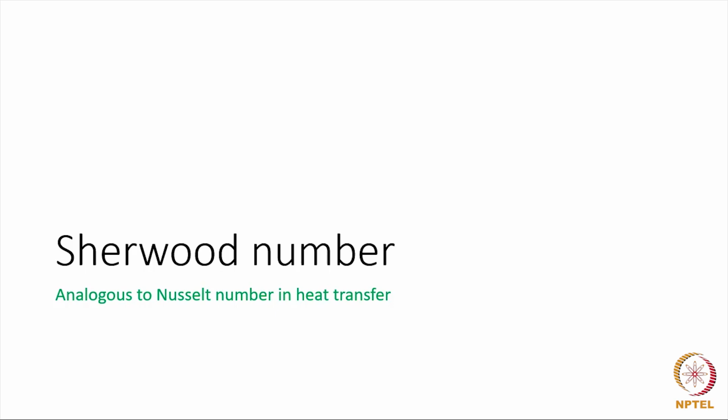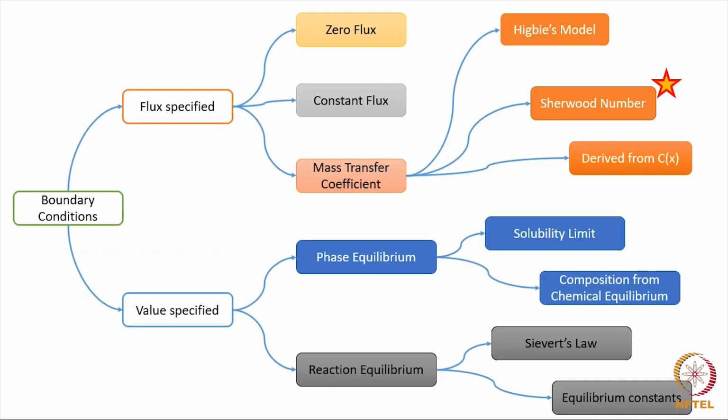Similarly, the mass transfer coefficient has units the same as velocity, and we want to convert that into a non-dimensional quantity so that we can arrive at correlations when we perform experiments. Such a non-dimensionalization of the mass transfer coefficient is called the Sherwood number. Here we put it in the perspective of the concept map for boundary conditions, which are sometimes given in terms of Sherwood number, which means we can then get the mass transfer coefficient, then the flux, and therefore the boundary condition.